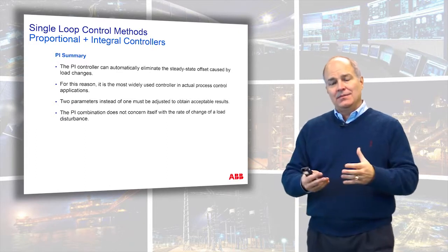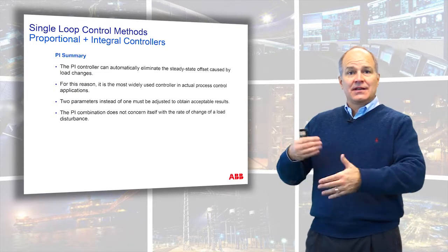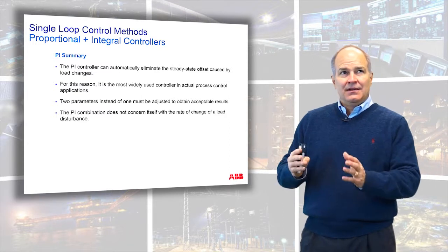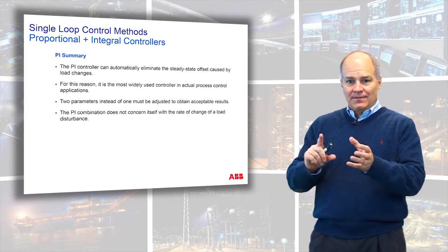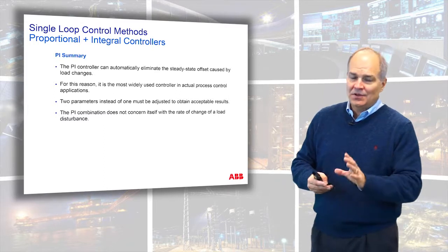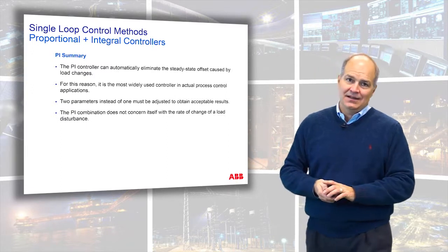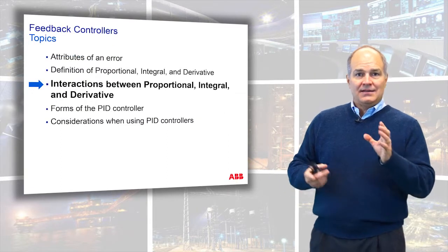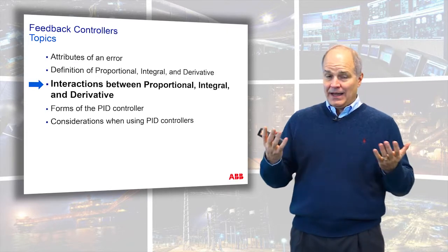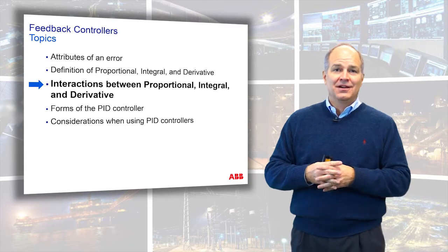Derivative, when added to the mix, does act as a lead, and I've used it when there's like a known limit cycle. I can adjust the output. Think of it like if you're timing a car, you can change the timing. That's kind of how derivative works. Most of the time that's an advanced use of the PID algorithm, and most of the times it's not needed. So the P and the I together work as a powerhouse, so you really get 1 + 1 equals a huge benefit to the automation world.